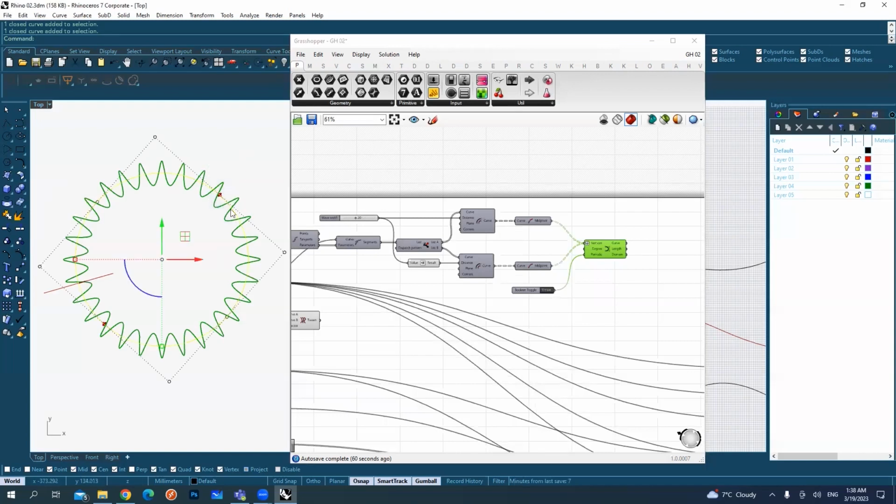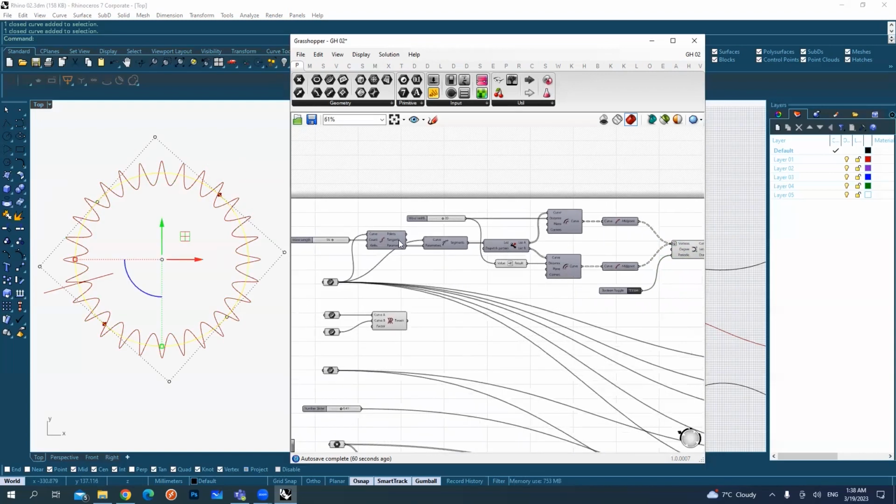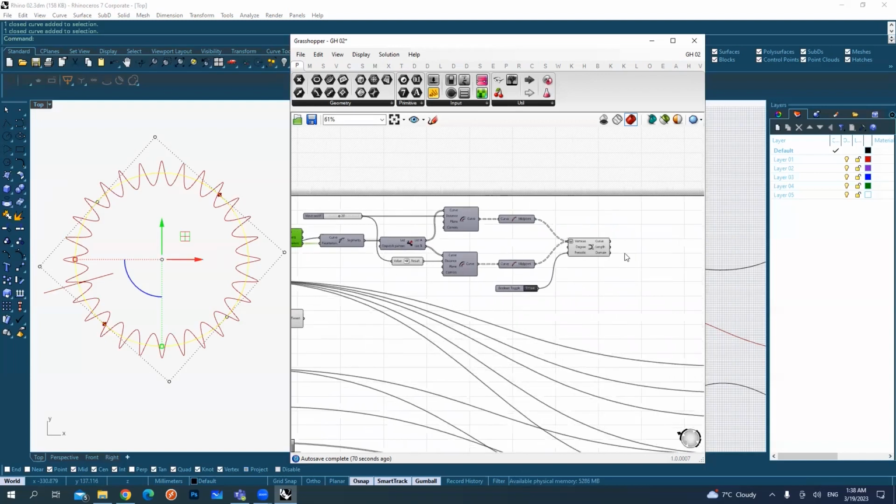Actually, the workflow or process of creating such designs is, after you create these with lines, for example we created this now using a line and applying some algorithms to the points, then creating this final line, then we can create it as a surface. When you are finished with the surface, you just convert it to a mesh. That's the next step, maybe after this class. When you convert it to a mesh, you can control how dense the mesh is and the quality of the mesh.